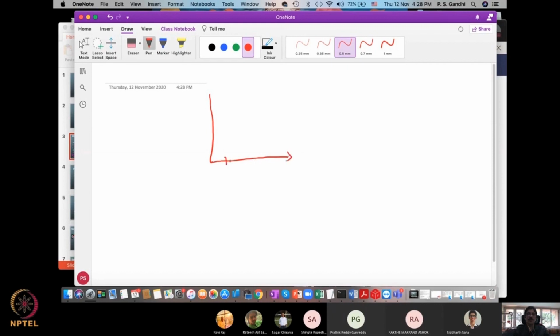This is my first sampling time, this is the second sampling time, this is the third sampling time, and so on. I have the first duty cycle coming up here, up to this point, then it will get updated and become something here, and over the sampling interval it is going to remain constant. That is an important thing here. From 0 to t, it has some value here, then from t to 2t, there is another value. This is how control is going on in my system.